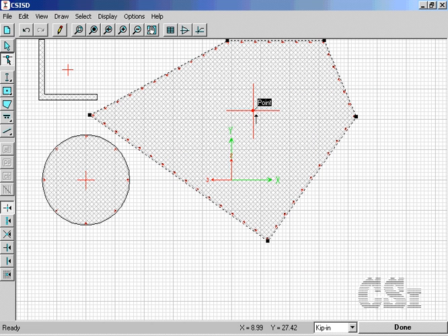At this point, it should be noted that all three of the drawn shapes constitute a single section, and though one of the shapes is steel, the Section Designer utility will calculate properties for ETABS based on the equivalent base material of concrete. It should also be noted that only the member 2-3 axes have meaning for ETABS, as the XY axes shown are local references only.